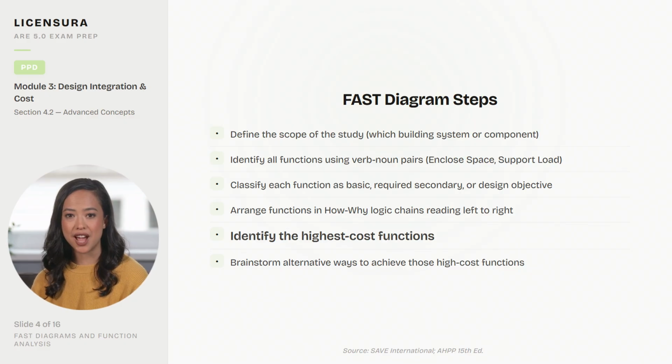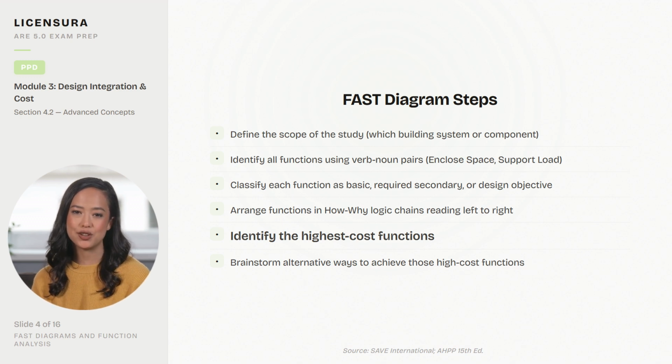This table illustrates how 5 VE decisions affect the triple constraint of cost, schedule, and quality. Switching steel to precast may save 10 to 15% on structure and could be faster to erect, but changes the aesthetic and connection details. Reducing floor-to-floor height saves on cladding and risers and speeds construction, but reduces ceiling height and MEP flexibility. Combining mechanical rooms eliminates equipment duplication, but creates longer duct runs. Standard curtain wall costs 30 to 50% less than custom, with shorter lead times. Deleting a basement saves major excavation costs, but requires relocating that program space.